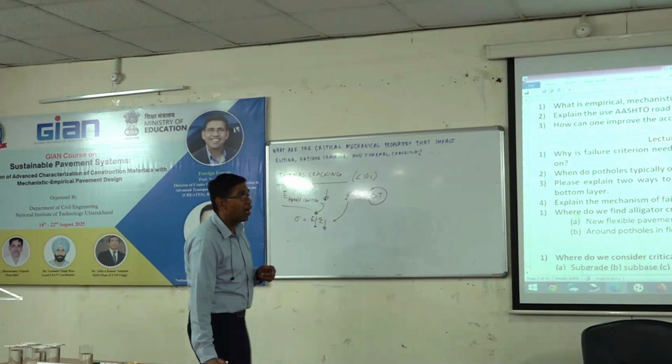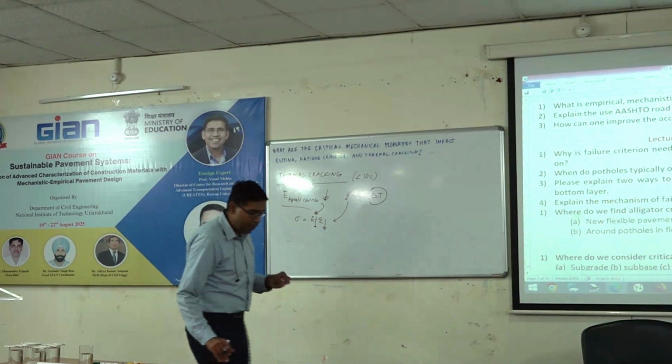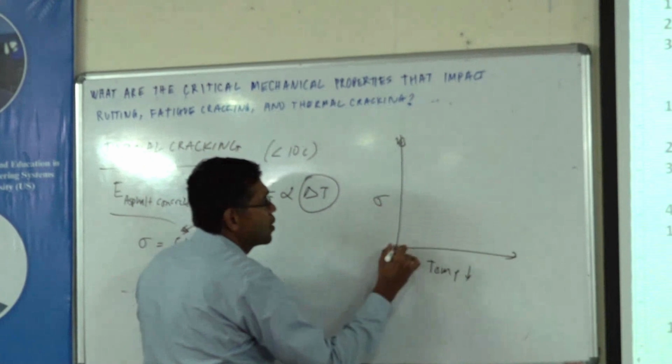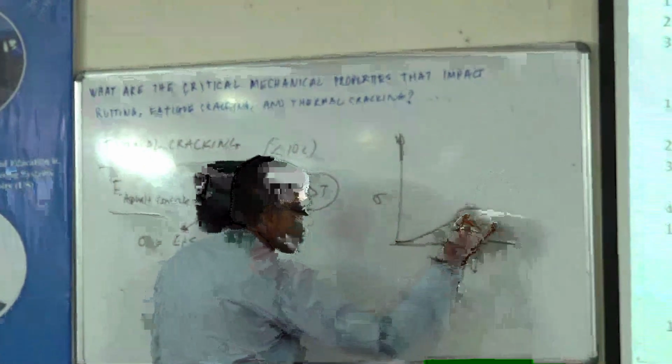Right. So the water infiltration thing is not it; this thermal cracking is purely not related to water. So you have this happening: your thermal strain, and when you have a temperature drop, stress, you have something like this.